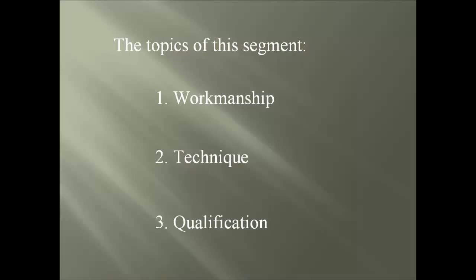And the last topic is qualification. Ever since the very first edition, it has been used by designers, engineers, and fabricators for the welding of reinforcing steel, with items like the WPS and welder qualification, retest procedures, period of effectiveness, how to record, and not to forget the all-important observation of the base metals, equipment, and even the contractors.